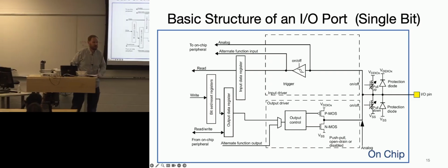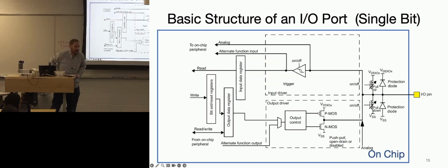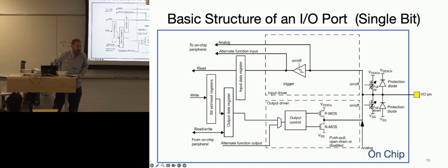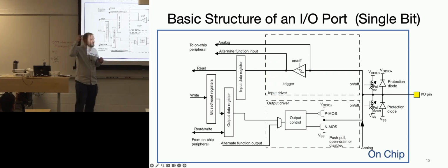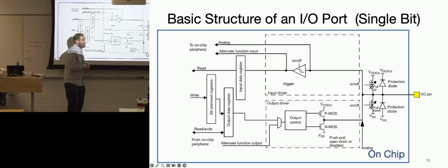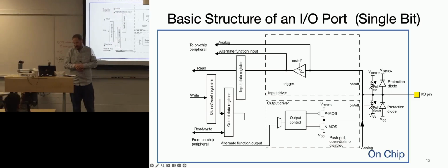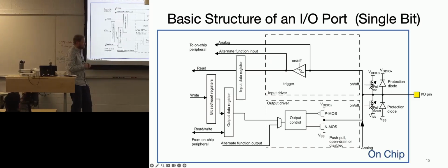This economics point might not be part of class, but why can resistors be smaller on chip as opposed to off chip? It's a good question. I was an electrical engineer once. I actually taped out chips at Intel and in other places. You can make really bad resistors using your diffusion, whatever. There's a silicon way to make really bad resistors that are actually kind of small, and as long as you treat them right, they're okay. If you want really good resistors, they also take up more space. Either way, you're taking up space.